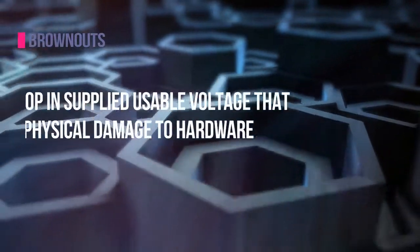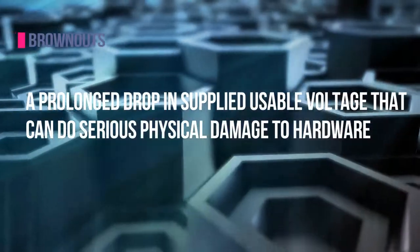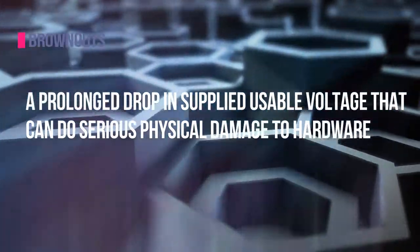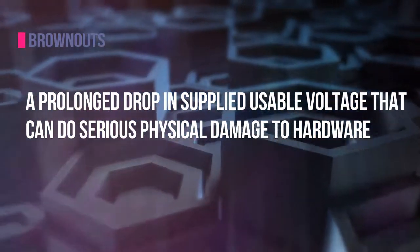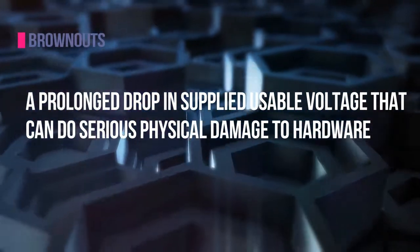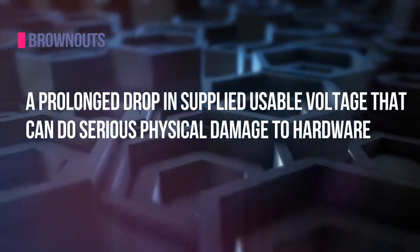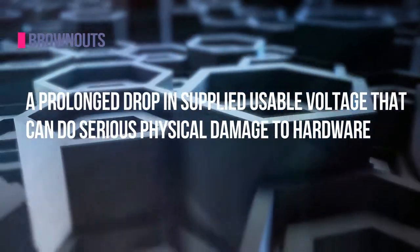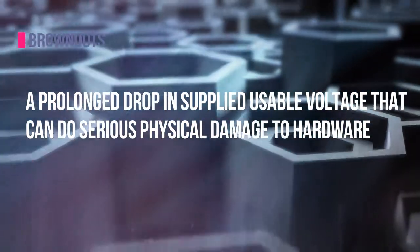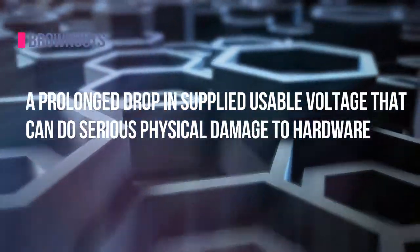Unlike a sag, a brownout is a prolonged drop in supplied usable voltage that can do serious physical damage to a delicate electronic component. For those who don't know what a sag is, it's basically a voltage dip. A voltage sag would last for like a second, whereas a brownout would usually last for a longer period of time, which, like I said, could cause some serious damage to any component within the electrical system.